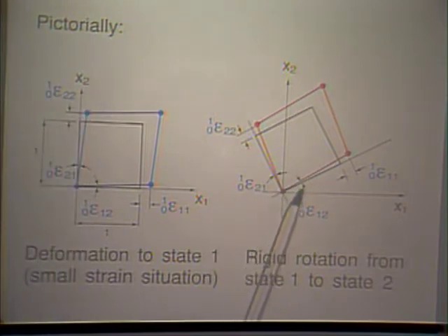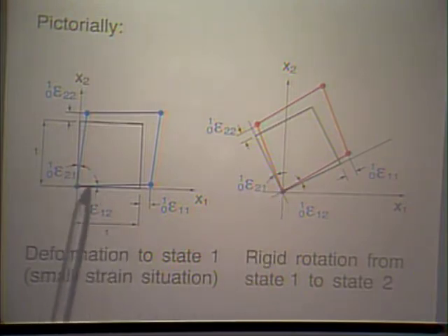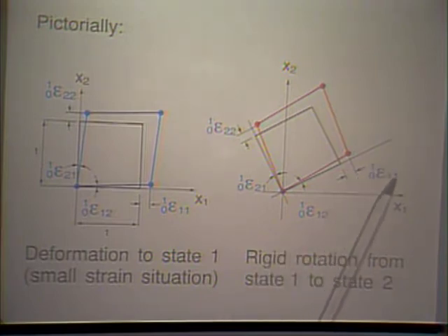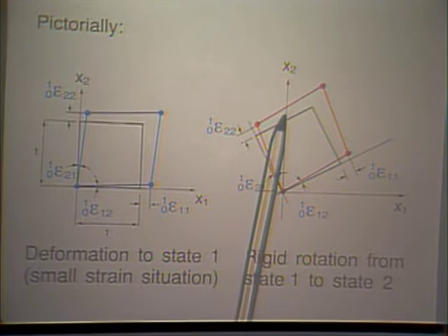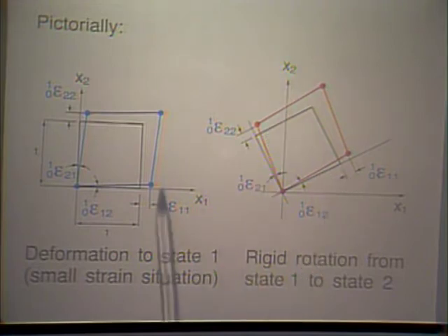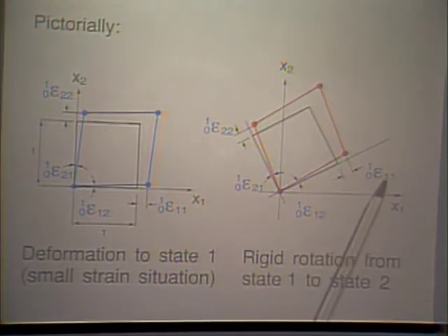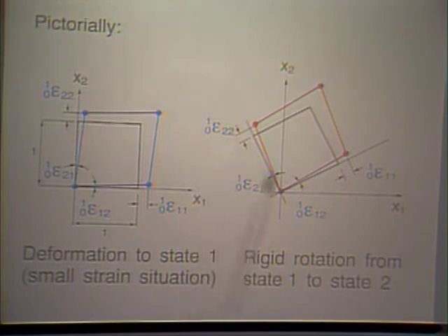And the total shearing is still the same as what the total shearing was here. Notice the Green-Lagrange strain components corresponding to the stationary coordinate axes 1 and 2 have not changed, because here this 1 and that 2 refer still to the stationary coordinate frame.